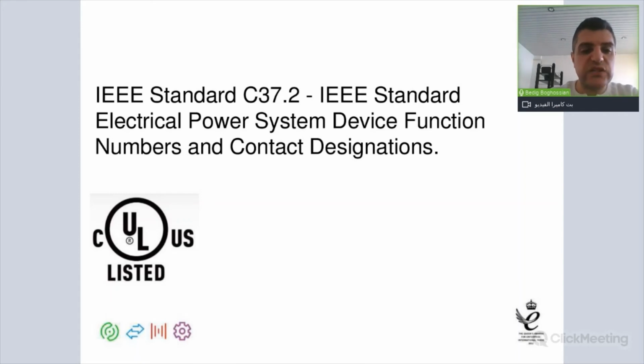The DSE GenSet controllers also comply with the IEEE C37.2. I'm sure you have come across many protection functions such as ANSI devices. And what are those devices? There are numbers for those functions which refer to specific protections such as earth fault protection, sync check, under voltage alarms.